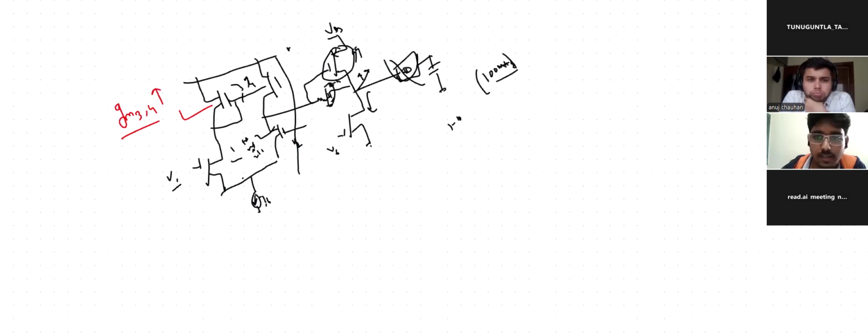In the first stage we'll have two poles now, sir. We can expect one capacitor here, say C1, and one capacitance here, C2. Assuming all the remaining poles are so far from the unity gain bandwidth, we can take two poles ideally. Do I expect two simple poles only from the first stage, or anything else? Yes, there will be a zero also, sir.